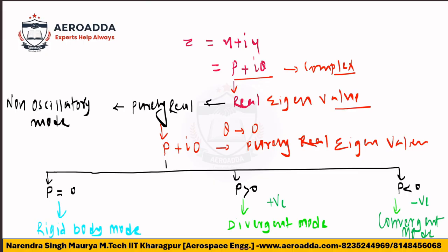If it is asked in an examination, one exam asked this, and it is also related to vibration. Convergent means it should come to its initial condition, amplitude should be zero, but without any oscillation. So what path will it follow? It will follow the exponential path, for both convergent and divergent. This is when the eigenvalue is real. This is very important.